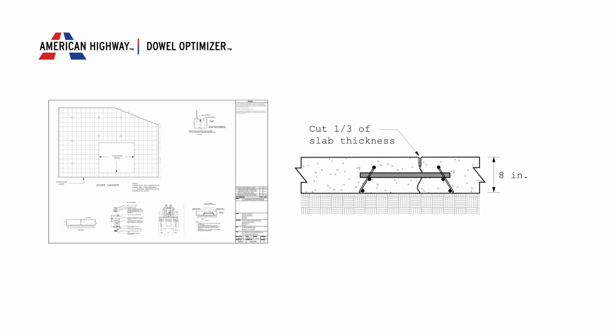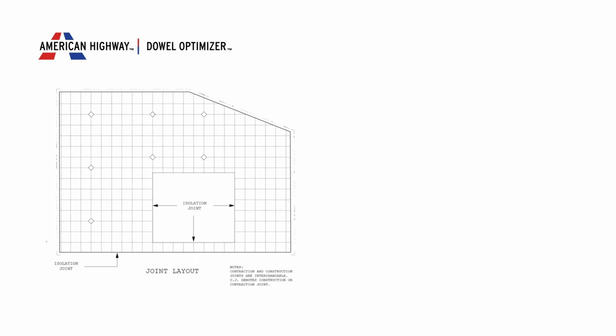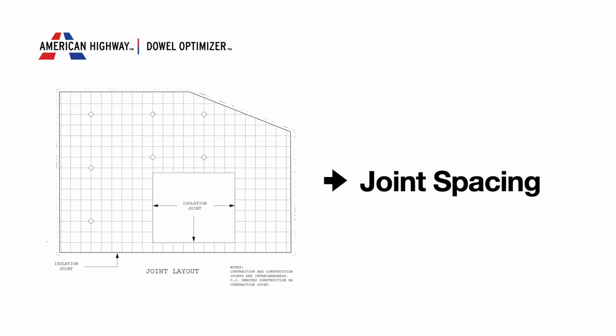For instance, the pavement or slab thickness is usually noted in a section view of the architectural plan set. This section may also specify the support layer material located directly beneath the slab. If a joint layout is included in the drawings, it can be used to determine the joint spacing. In many cases, these values are also reiterated in other parts of the plans and specifications.